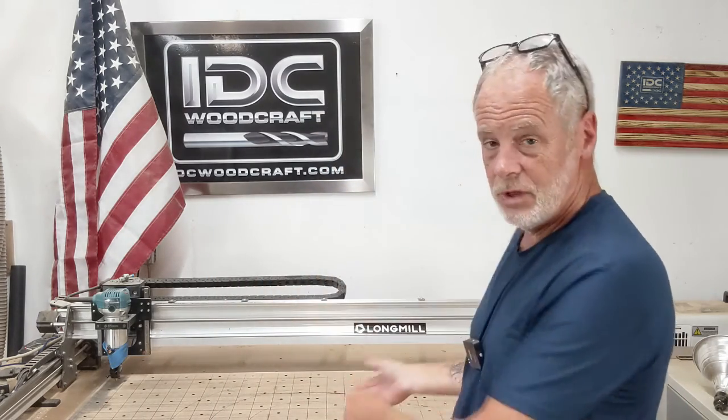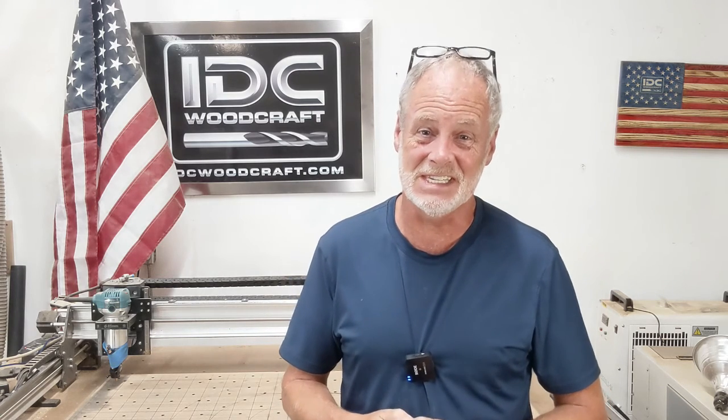Once the G-code has passed through the post processor and the post processor has inserted the necessary codes into that G-code, it comes out the other side written the right way for your CNC router. For example, the Longmill MK2 here, or whatever you have. And from there, you take that G-code and you put it into your control software, you hit the start button, and the machine starts doing what you want it to do to carve that amazing CNC router woodworking project. You don't have to understand how a post processor works. You just need to know that you have to have it.